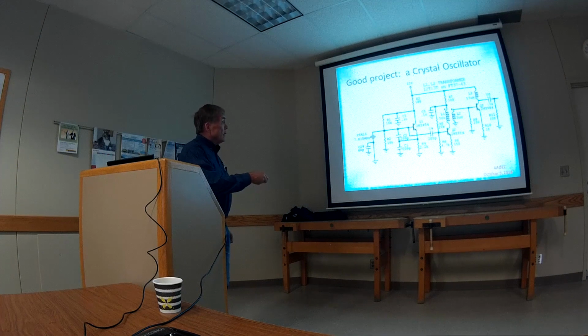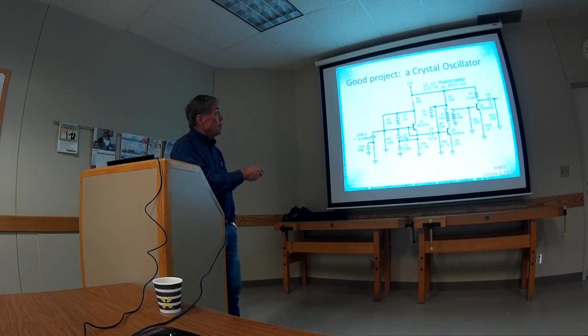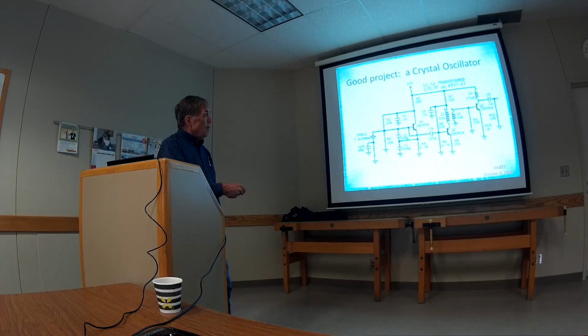And then you see the Colpitts part of it, the heart of it, is this transistor, the Q1 here, and then this part of it right here is the Colpitts. This is a buffer that's added onto it too. This is really a full transmitter. If it's crystal control, if you want to make a full transmitter and hook a low-pass filter out here, you'd probably get a watt or two out of this one, just the way it is. You have to key the 12 volts or some other way of keying it to turn it on and off for CW.